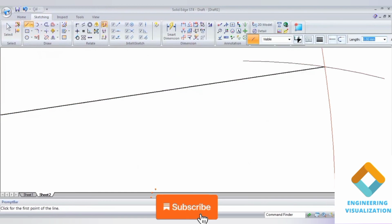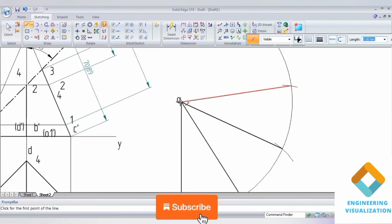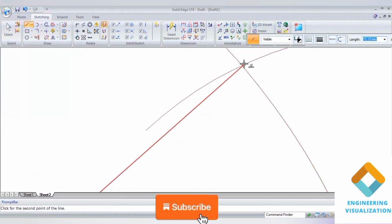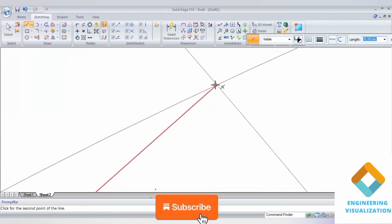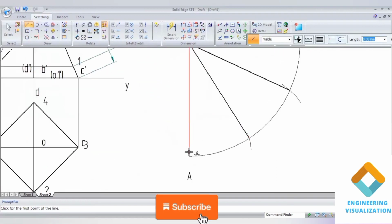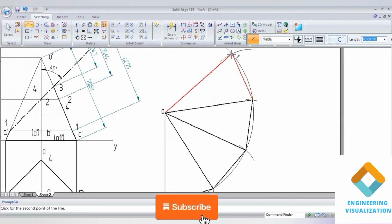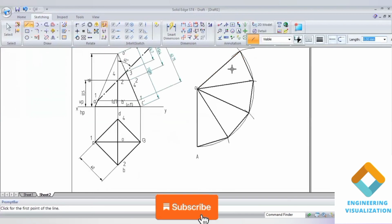Connect all the arc cut points which you have cut, using vertical lines. Like this you can connect it. If you're finding any disturbances during the video, you can neglect them and concentrate on the video so that you are able to practice it. Like this you can construct, because it has four sides since it is a square pyramid. So join it like this.